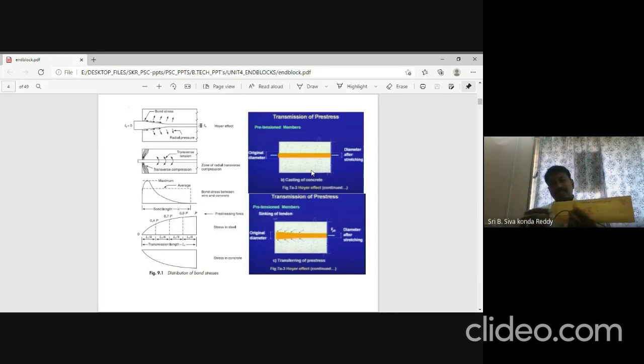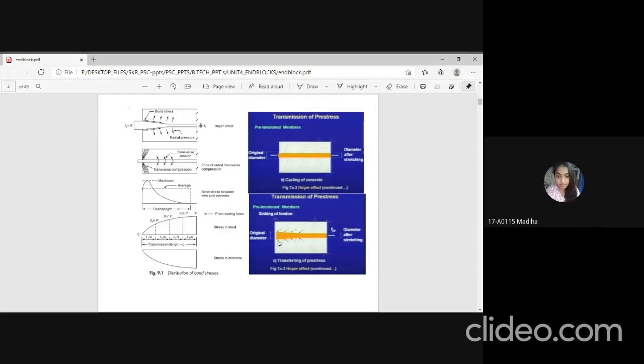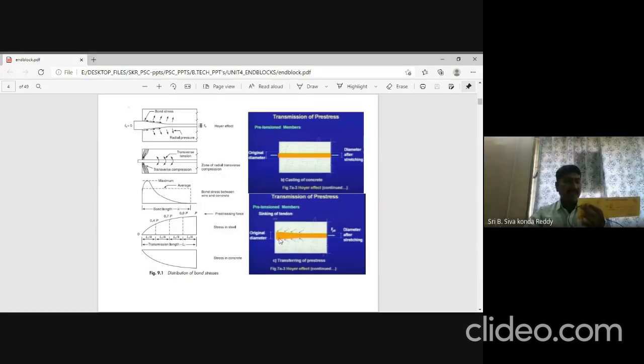Gradually, as this starts swelling out, you're going to see some wedge action. This wedge action is shown in this figure, where my mouse is pointed. Can you see my mouse pointer? At the end you're going to see some wedge action. As this wedge action is formed, it exerts some pressure on the surrounding concrete, and this pressure would be your bursting tension. Your cable is trying to reach its original position, and you have a concrete interface which opposes this. Got it?